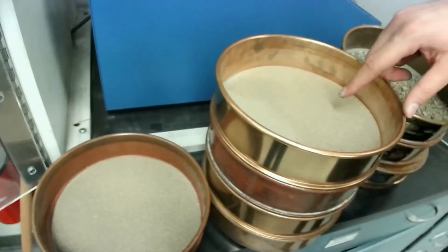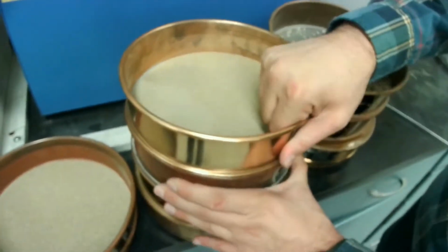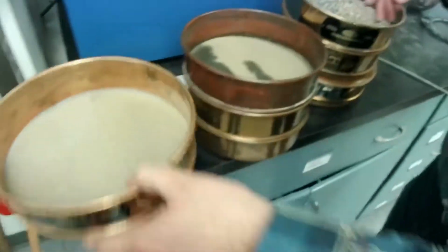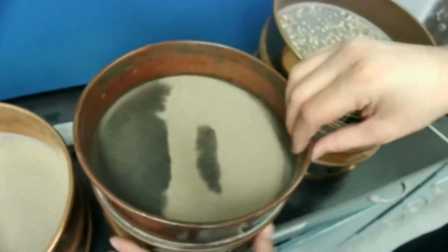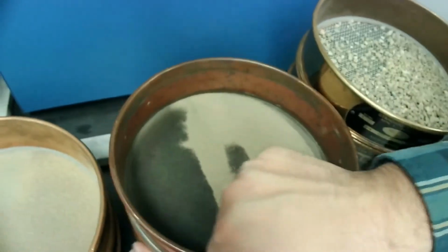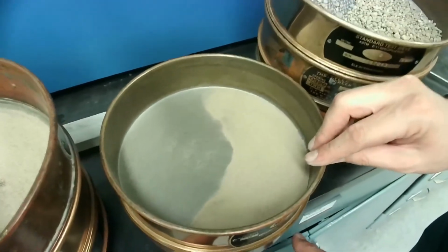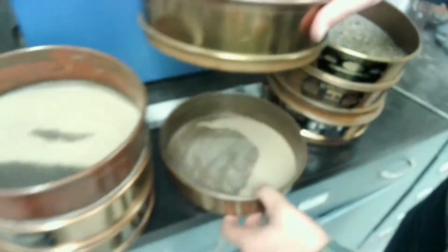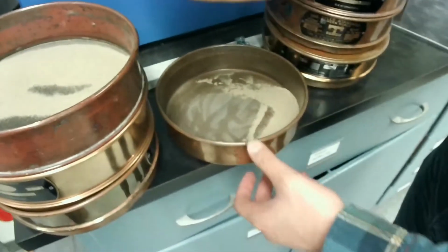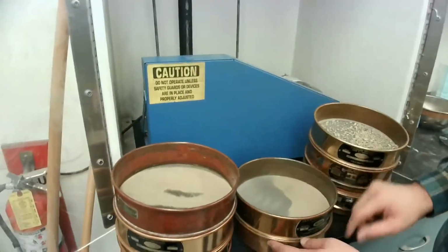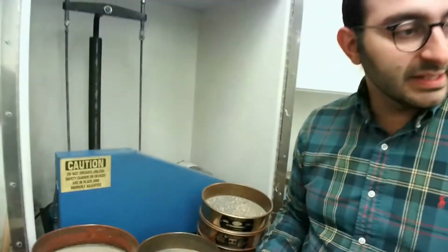So again, this is our number 60 sieve. So as we're going down, stuff is getting way more finer. Then here we have our number 100 sieve, so a good amount of that, and this is the stuff that's retained on our number 200 sieve, as you can see. And we have a little bit retained in the pan going through the number 200 sieve, basically meaning that we still had some fines that did not get fully washed in the washing process.